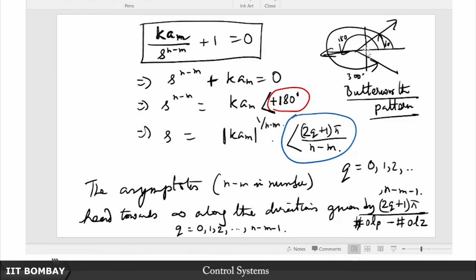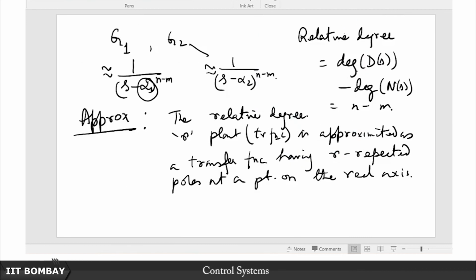So we might want to exactly find out through which point on the imaginary axis it migrates to the right half plane and what is the exact value of k, the critical value of k at that point. So that is another refinement of the root locus which we will be interested in finding out.